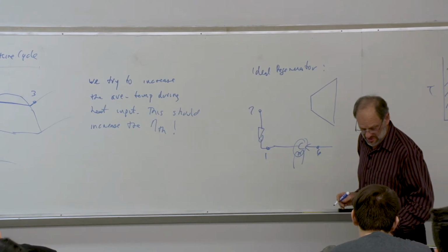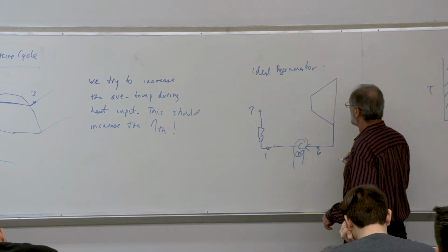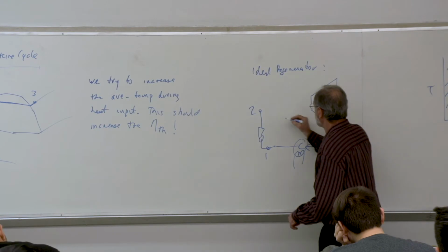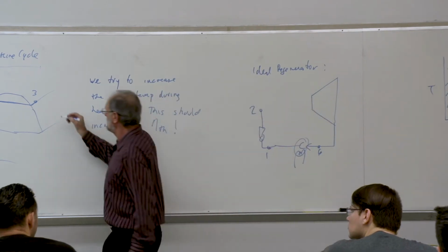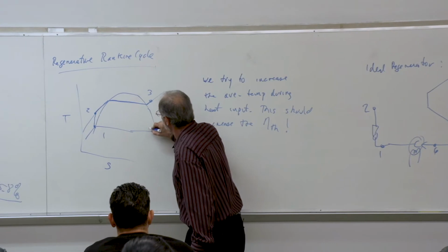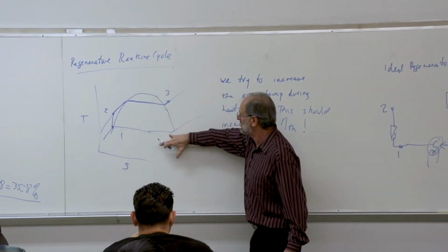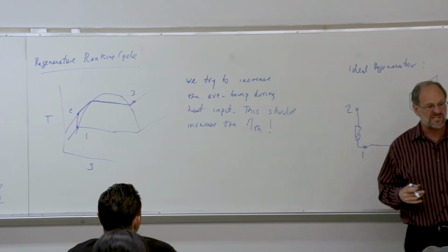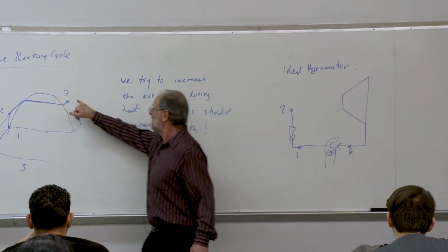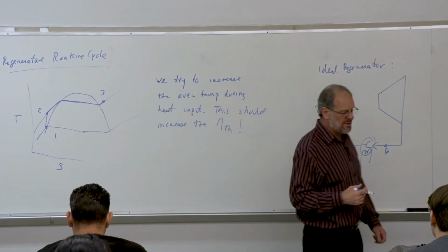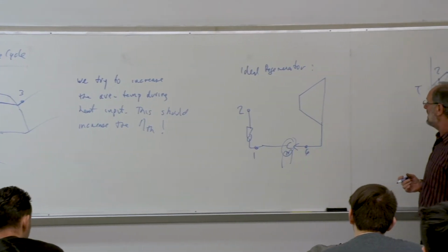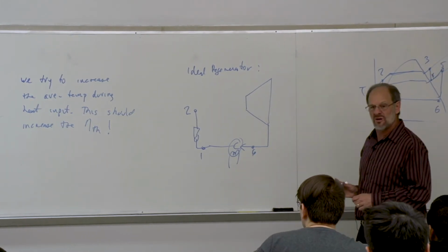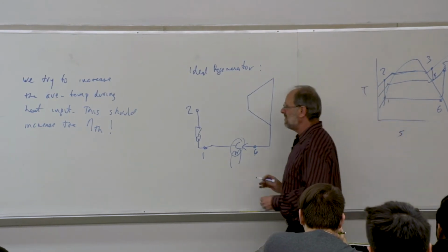the discharge from this turbine is 0.6. Okay. And now let's look at the regeneration process. So you'll see that eventually when we expand through the turbine, the temperature is going to be quite a bit lower. But where the steam goes into the turbine, the temperature is actually pretty high, and it's even higher than the temperature we have at point 2.